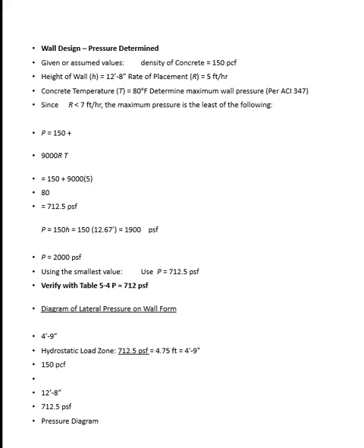So you've got a wall design, you've determined the pressure that we've already talked about. You can go through and calculate, again using the criteria we just talked about, the pressure that's going to be applied for that wall design, right? And again, table 5.4, and that's still coming up, but you'll have it in your printout, will give you a guide. Remember, it has to be at least 600. In this case, for this first calculation, it shows 712 PSF after we go through the calculations.